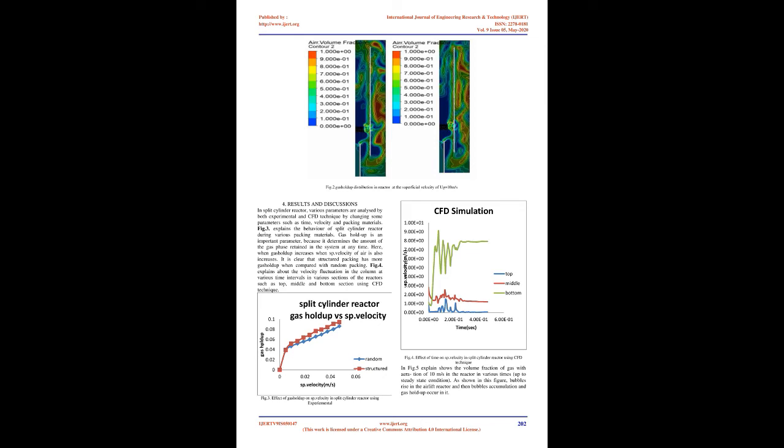4. Simulation. In the simulation, the gas and liquid phases were air and water, respectively. The governing equations and constitutive relations have been discretized based on the finite element method. At T=0, all of the reactor volume is full of water and the volume fraction of air is equal to 0. The simulation will reach steady state after 0 to 10 s.